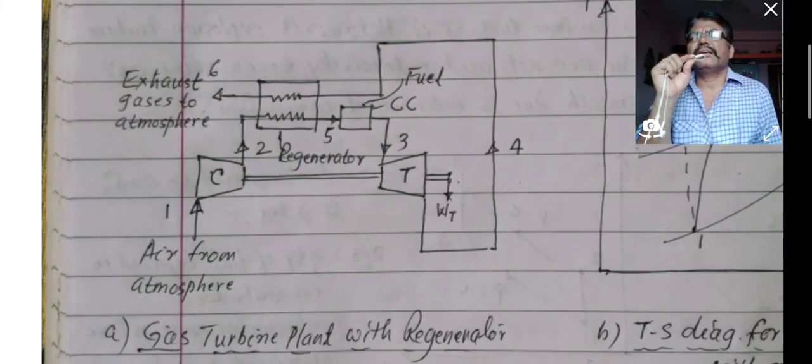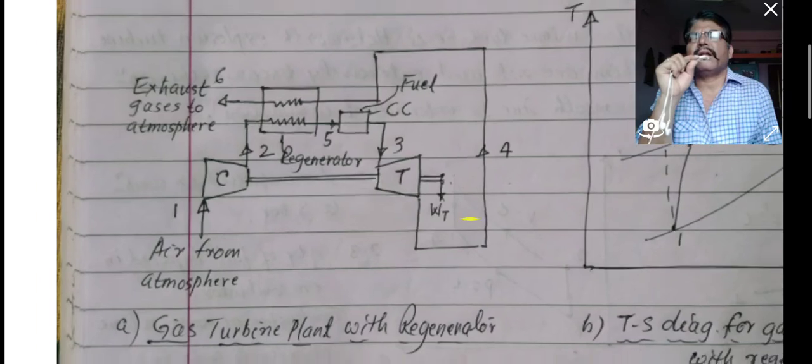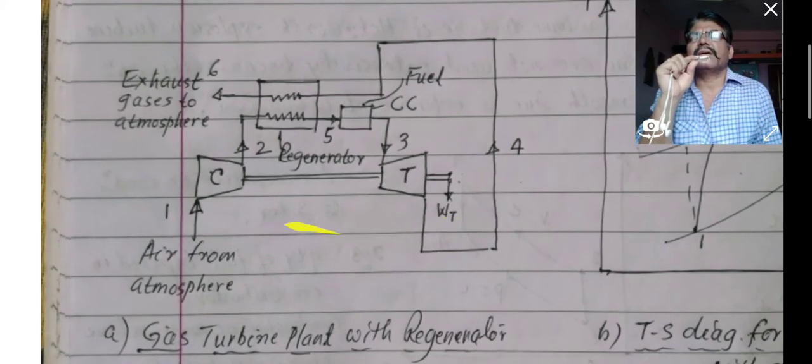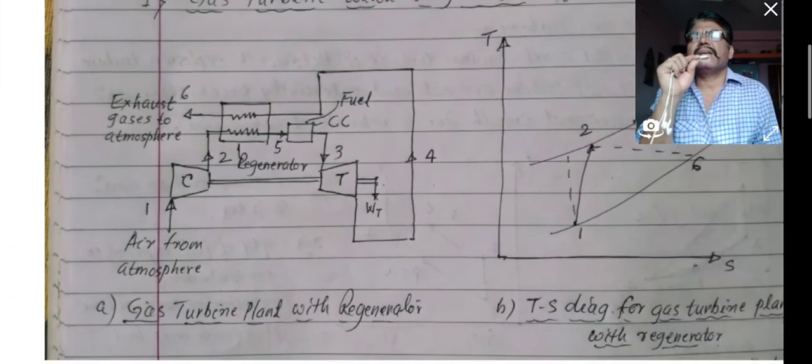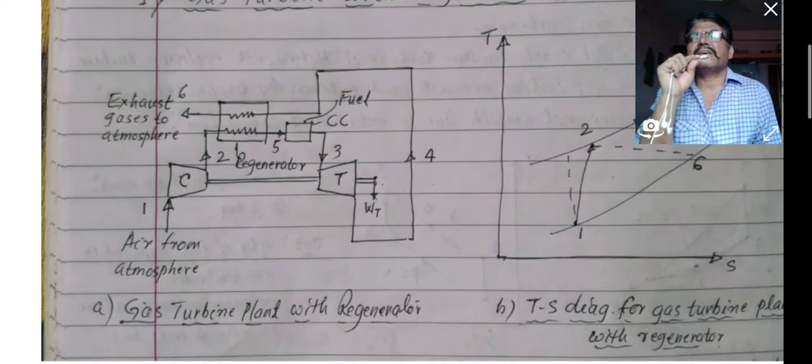In that the fuel is provided into the combustion chamber, inside of which the combustion takes place, so that the combustion products go to the turbine. When that material goes to the turbine and falls on the blades of the turbine, the turbine rotates, it means the mechanical work happens inside it. And as the turbine is connected to the generator, there is generation of electricity.